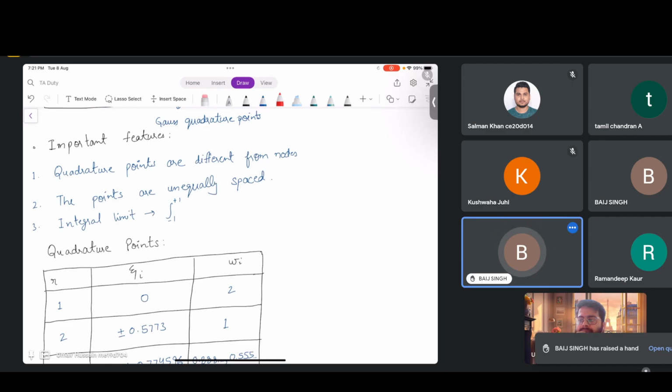We have a four-noded element, and we say that we have a reduced integration element, that is S4R, or in terms of ANSYS, C3D8R in terms of solid elements. Then how do we say that? Which point is that which incorporates the contribution from all four nodes or all eight nodes?